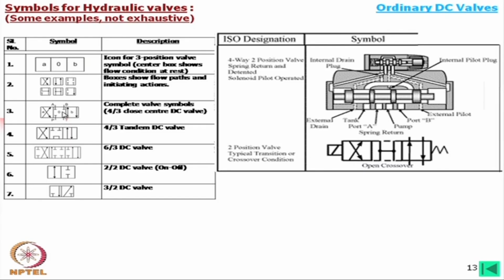Now, if we would like to compare with this valve, suppose with these connections, what is the difference? In that case, if you leave the valve, then automatically it will come back to this position. Suppose we are using full open center, but in this case it will be full open center only if you use the detent position. That means, you have to regulate this actuator in such a way that it will be at the detent position. So, it is operating conditions, no neutral position, either this position or this position, only in the detent position it will be there.